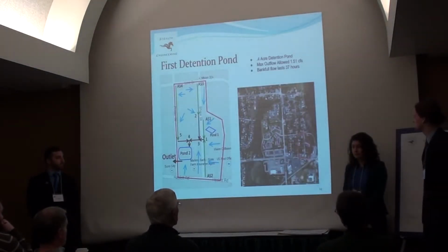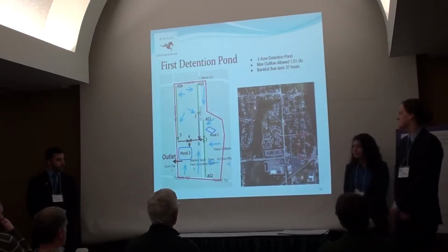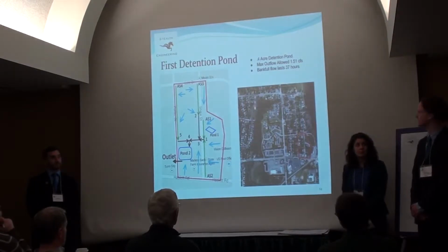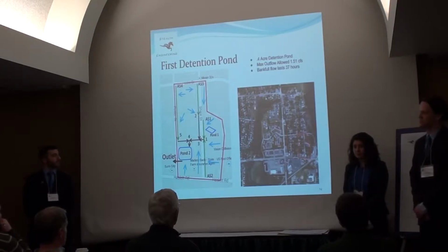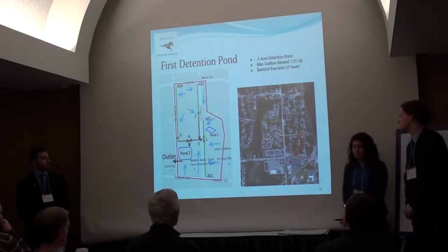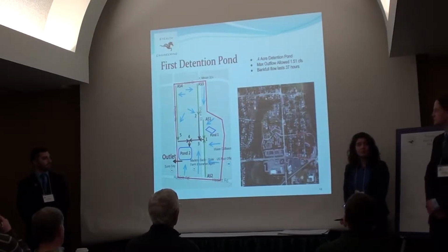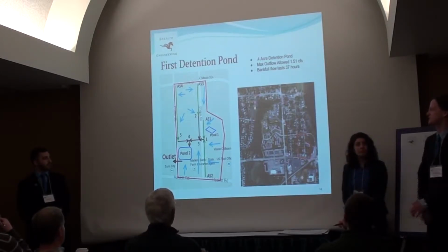So our design was to split this area we just previously shown into two separate areas and handle them with detention ponds. This area shown in red is 10 acres roughly, and pond 1 is a no outlet retention pond, which would take care of exactly 1 acre of land. So with pond 2, we use swales and pipes with manholes at each start and end of the red arrows, which represent pipes, and the green arrows represent swales. So this 10 acres of land was routed through pond 2, which is a detention pond.